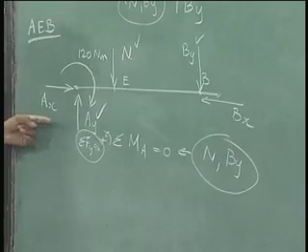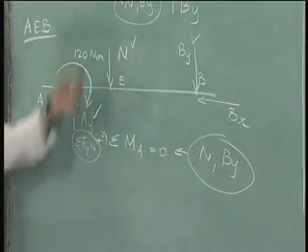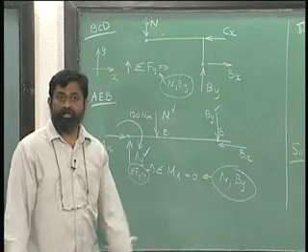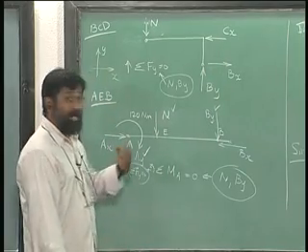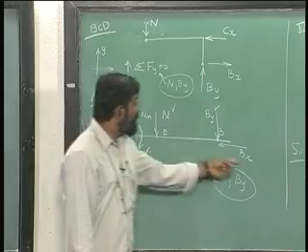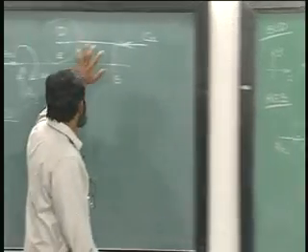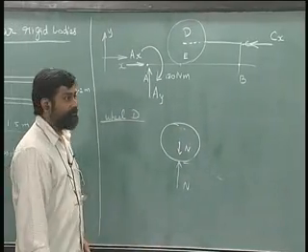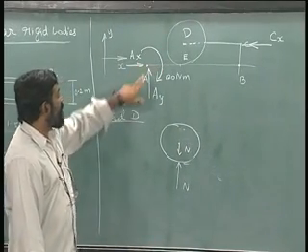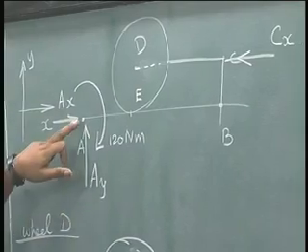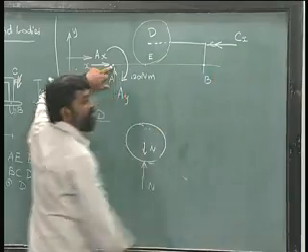Okay. So Ax equals Bx, Cx equals Bx are the two equations I get. I need 3 equations because I have Ax, Bx and Cx. How do I get the third one? I will go back to this guy, and if I take moment about this, I avoid Ax and Ay, there is only Cx that needs to be solved here.